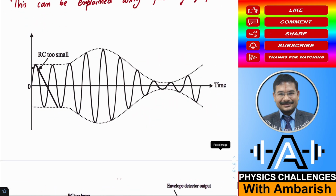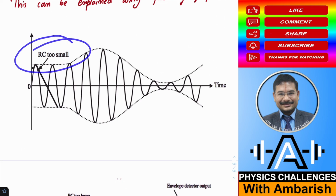A picture is worth 1,000 words, so I just skipped all those 1,000 words and straight away cut to the chase to the picture. What will happen? See, if RC is very small, it will hit the peak, and then of course diode will get cut off, but then the capacitor will discharge almost immediately. So you wanted this to discharge slowly so that it is able to capture the next peak, but instead of capturing the next peak, it is just drowning all the way to zero. So the capacitor will get almost instantaneously discharged if RC is very small, right?